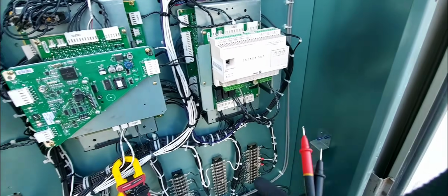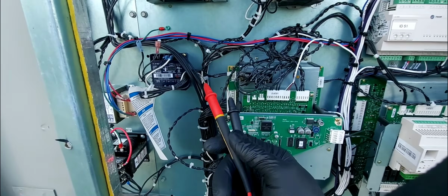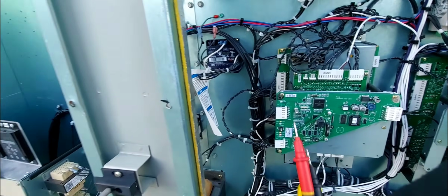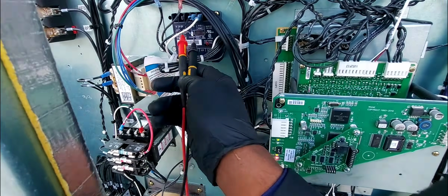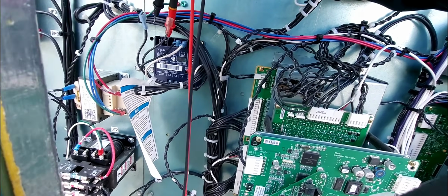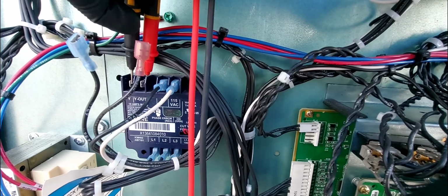You have all these control boards right here. Why can't you have a separate input so that if my phase monitor is tripped or open, or there's a problem with my phase monitor, I get a separate alarm? Come on, Trane. Your unit costs mad money. Like this unit costs mad bread. It's expensive. All right, so I'm going to go across the contacts right here, and I'm not getting any continuity, guys.